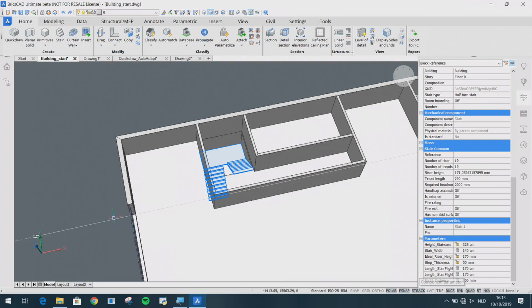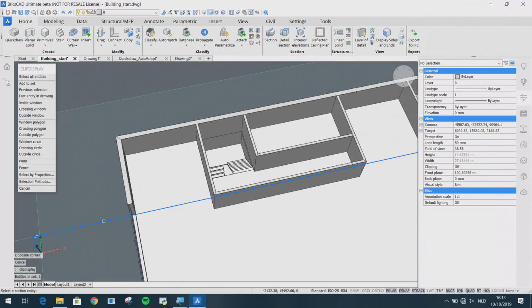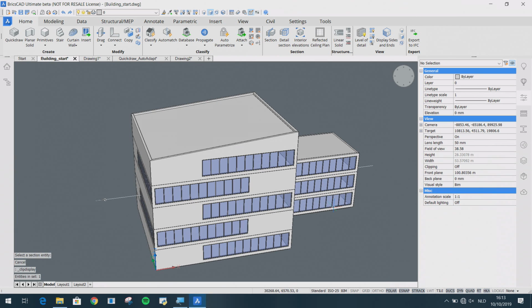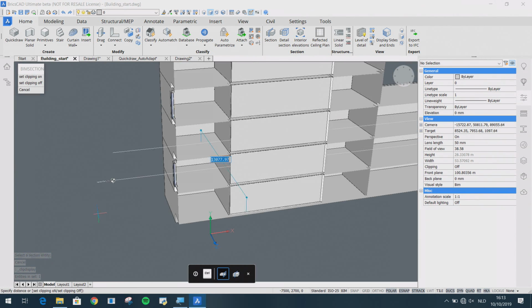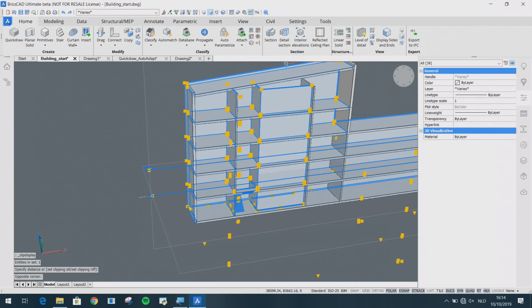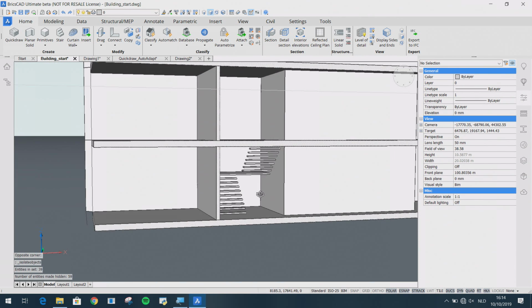So of course, again, as with the window, we have one stair. We need stairs to go all the way up to the top floor of the building, and again, we could recreate this stair, we could try to copy and repeat it upwards, but again, we think repetition, then we suggest to use Propagate, and that's what Wouter is also doing now.